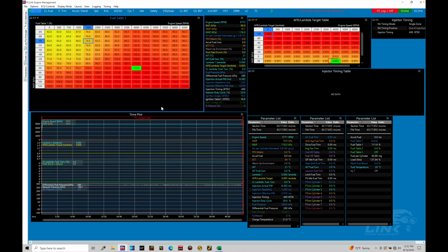But drag racing is very specific because when we launch the car from a stationary stop point, we get a very high calculated wheel slip, or the difference between our driven and undriven wheels. So front wheel drive car, front wheels, that's your driven speed. The rear wheels would be your undriven speed. When we launch, we have a huge amount of generated wheel speed to get going. The rear wheels are barely moving. So we calculate this couple 100% slip.